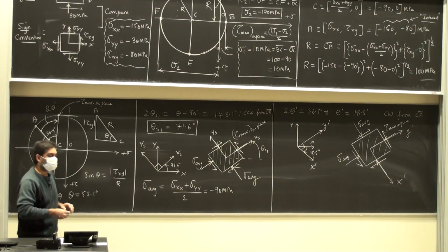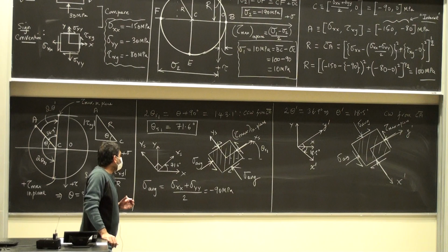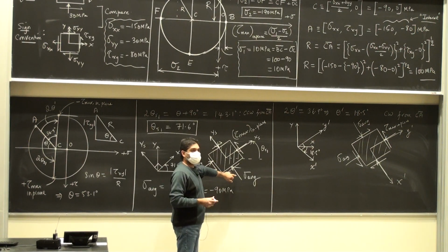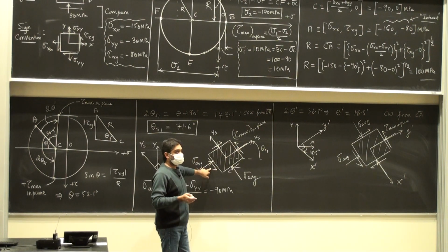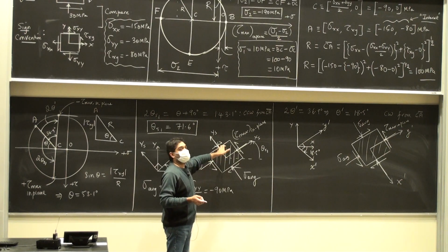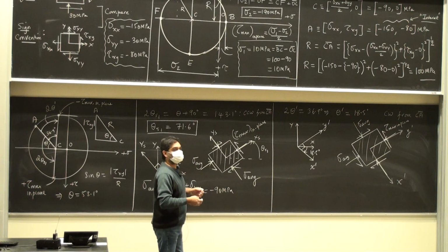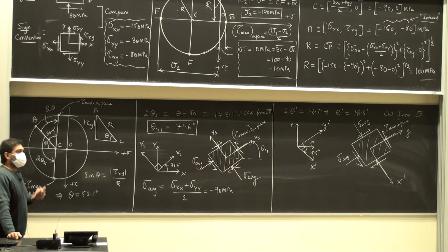Yes, sir. So that's regarding the ones that are going like that, which are going to go counterclockwise. But then what about the ones on the top? Wouldn't they be the opposite to make it go counterclockwise? What do you mean? Like the tau max in plane that's going like that on the top and the one that's going like that on the bottom. This one and that one? Yeah. They have to counter the couple caused by these two. If I look at this one, there has to be an equal and opposite one on the back. They are causing a couple which is clockwise. To counteract that, I need to have equal and opposite on the top and the bottom, which will cause a counterclockwise couple. This was the same thing that we did when we drew volume elements.